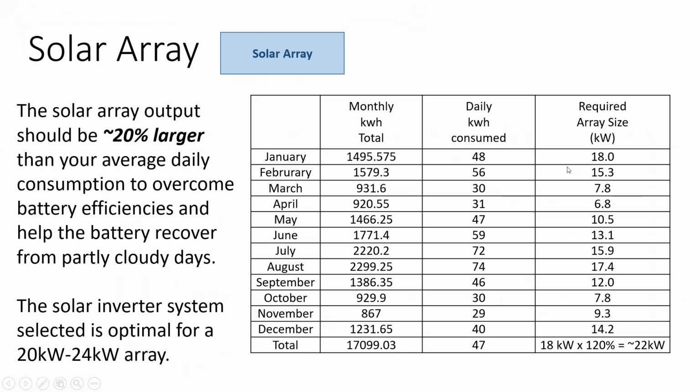And so by going from month to month data and taking our charge data from PV watts and looking at the bottom end of that curve and setting a maximum depth of discharge of 80%, and then getting our average daily depth of discharge of 35%, we can hone in on an appropriate operating range for whatever flooded lead acid battery type we select. And it's a very similar process for AGM or gel lead acid. It's just that on those, we're paying more for not having to do maintenance.